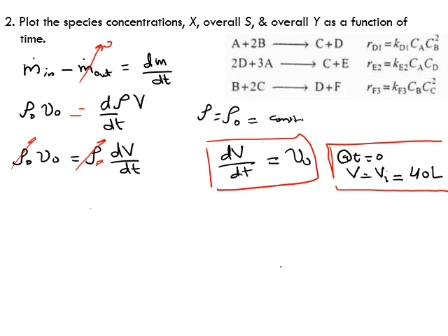Right, what about x? Okay, so we have B initially charged, so I believe that x should be written for B. So what does xB equal? Well, x is related to the number of moles or molar flow rate. Here for B it's a batch system, so it's NB initial minus NB, divided by NB initial.